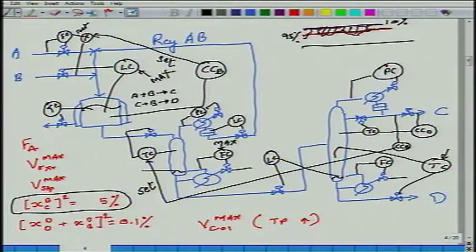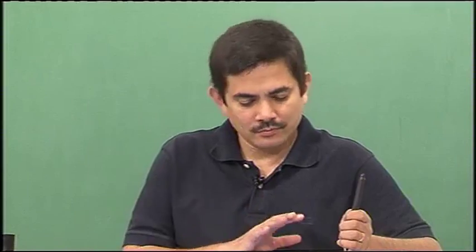What would I do? I would say, well, to maintain this level, this is unconventional. Usually you are maintaining levels using flows, in flow, out flow, some kind of a flow. Here you are adjusting a temperature, this is quite unconventional. So in this case, we will need to make sure that the set point which we are setting is not maxed out. So what will happen is, when I receive the instruction from top to maximize production, we will still have to leave a little margin. Temperature will have to have some margin.